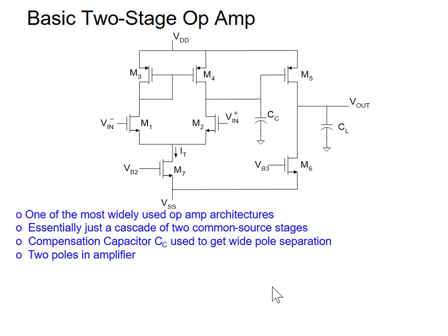Is it hard to pick that 0 up? So what did I do here? I did it by inspection, and I found the poles and the DC gain. But if there's a 0 present, we're not going to find that 0 because this method only finds the poles. So how much work would it be to find that 0? Not too much. What would I do? Would you use this model to find the transfer function? Yeah, we already have the model there. So instead of trying to write down these things by inspection, we'd sum currents at those two nodes and eliminate the voltage on the internal node. Make sense? So, not difficult to do.